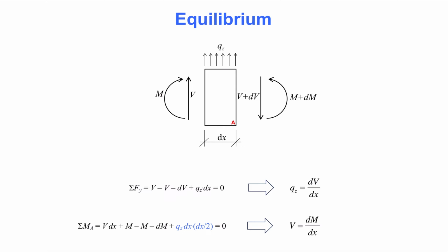On this slide, notice that the distributed load, QZ, is in the upwards direction. Also, notice that a shear force is introduced, in addition to the bending moment stemming from axial stress. It is not possible to establish equilibrium for this element without shear forces. This is indeed one example of recovering a shear force that is formally outside the formulation of the boundary value problem, which omits shear stress.